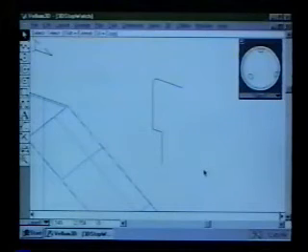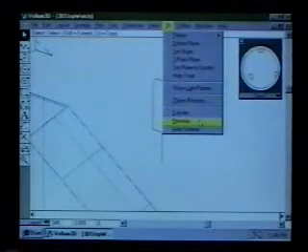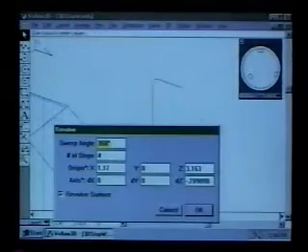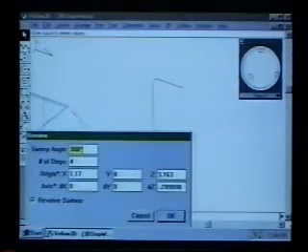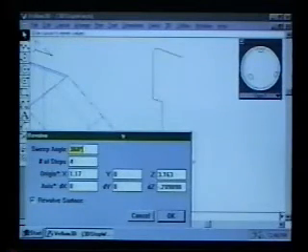And then we'll take this feature, just the contour, and we'll revolve this. We'll use the revolve command. We do want to take it through 360 degrees, and the revolve, we'll go ahead and have it have 4 steps, and that's fine. Now it wants to know the axis of revolution. That's what it's asking for. Well, the axis of revolution, because I have this little asterisk here, the asterisk means use the cursor to enter the values.